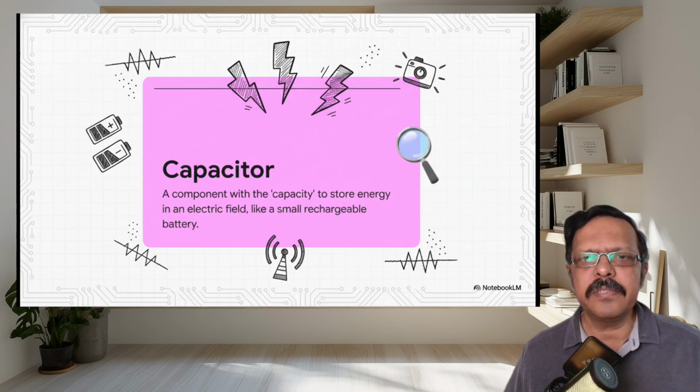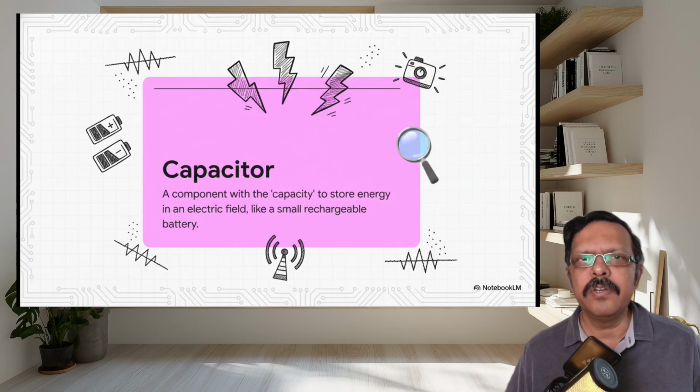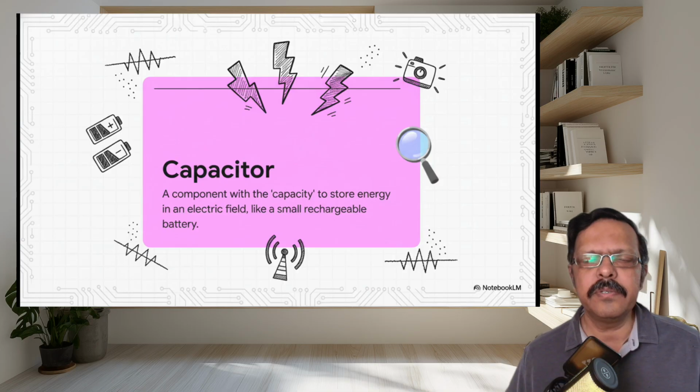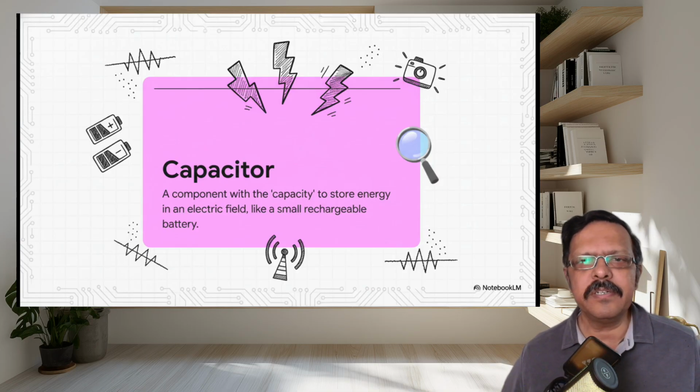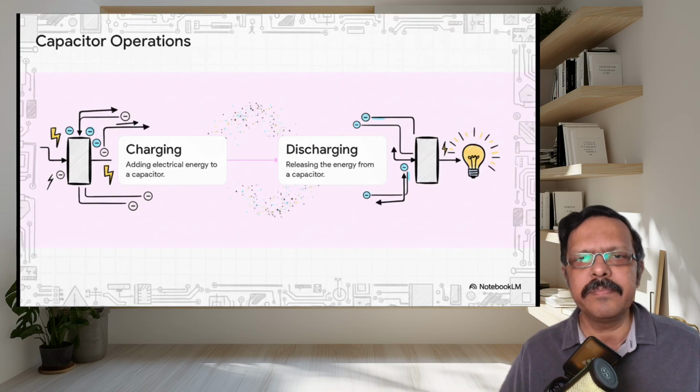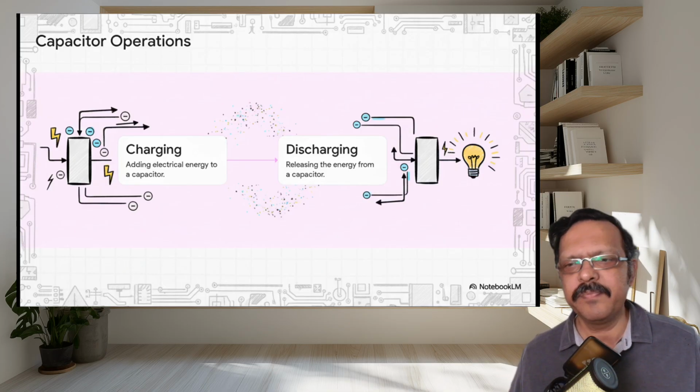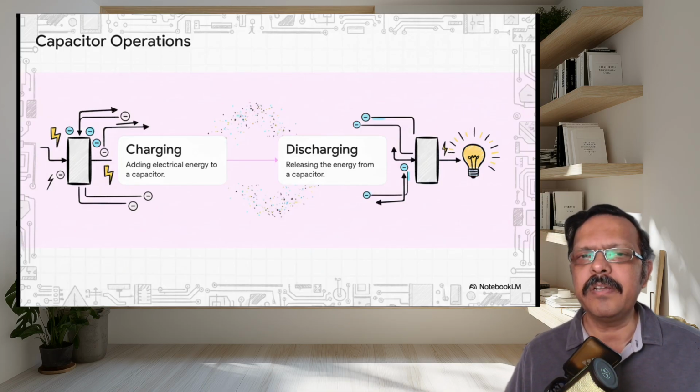Capacitors. So capacitors are everywhere in electronics. They are inside filters, power supplies, audio circuits, radios, you name it. A capacitor is essentially two plates separated by an insulating material called a dielectric. It's just two plates, and its job is simple: to store electric energy by holding a voltage across its plates. So that is the interesting part of a capacitor.